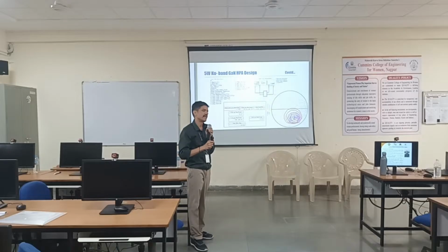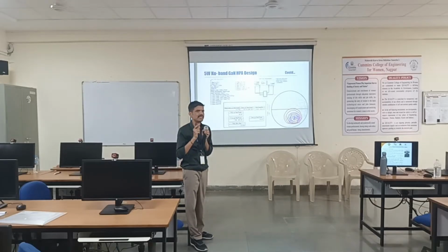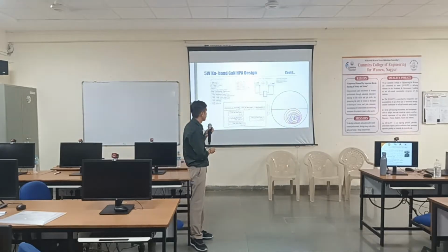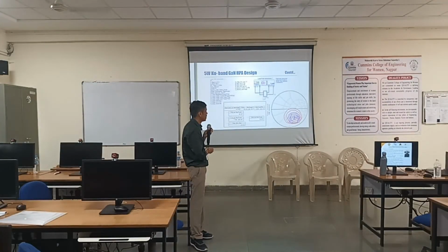So doing load pull analysis is the catch-all for PA design. The moment your impedances are close to 50 ohms, your design job will become simple. So make a note of this.